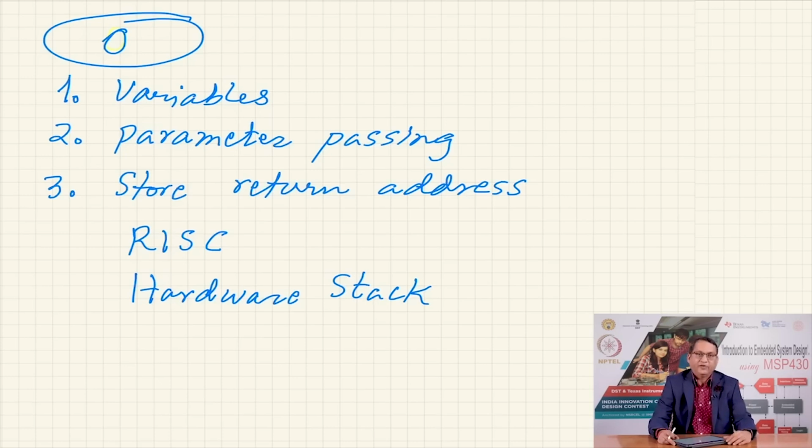In the case of a hardware stack, the storage is limited, usually 3 or 5 return addresses, and therefore you cannot have too many nested subroutines in such microcontrollers which do not have RAM, and instead have a dedicated hardware stack.